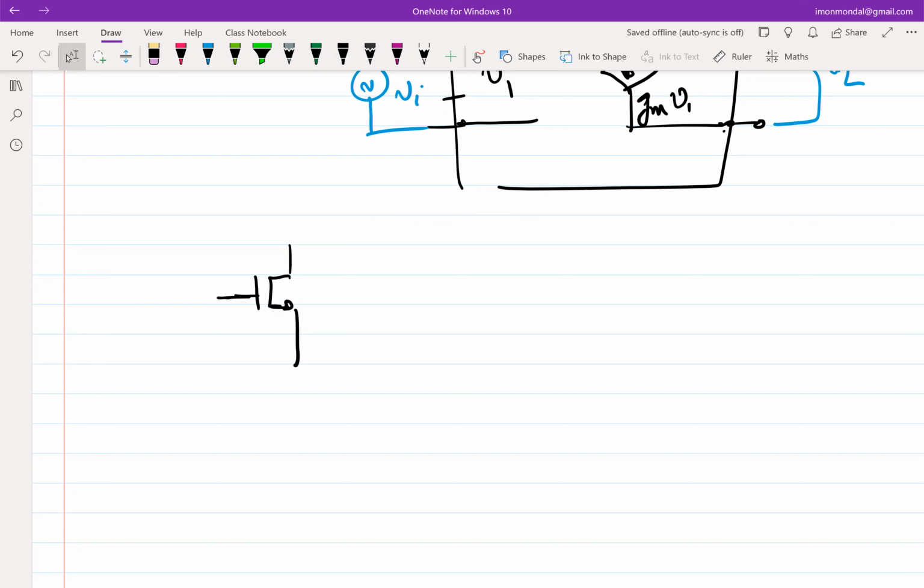Yeah, you need to give a threshold. You need to give a voltage which is more than the threshold voltage between the gate and the source terminals, right? So how do I do that? I apply a voltage source between, let's say, the gate and the source. And this, let's call this VGSQ. And VGSQ has to be greater than threshold voltage. Fine, the transistor is on.